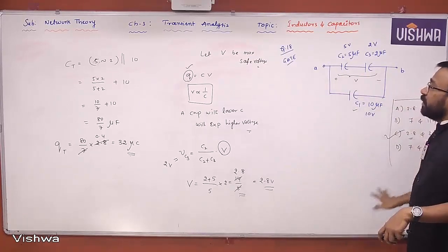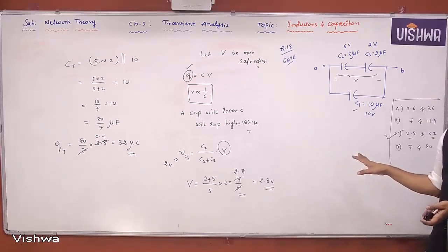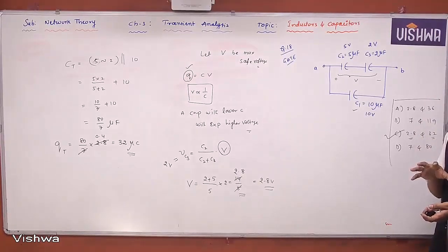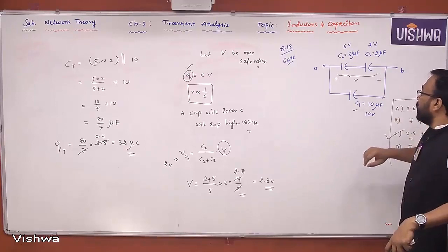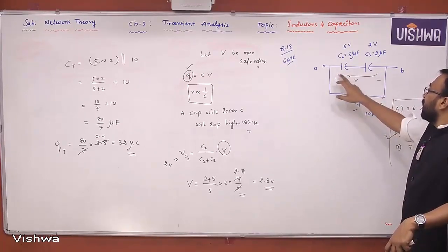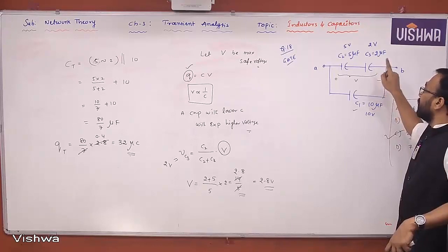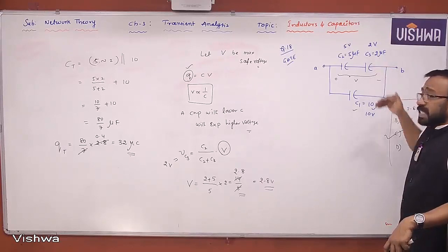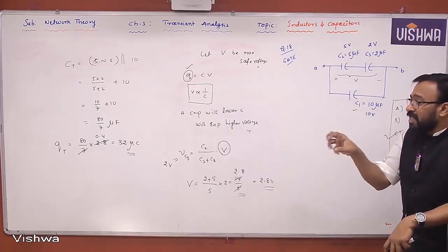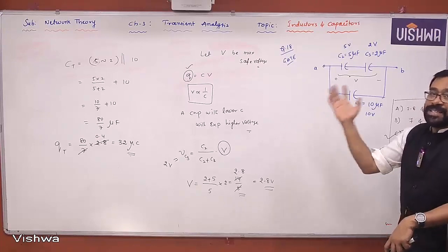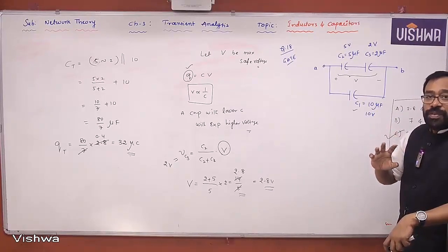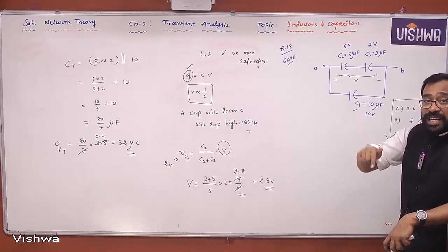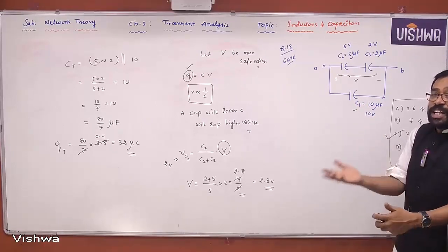So therefore, my dear students, you must be very careful while answering the questions. If you learn the concept, then you can answer the question in any form in which it is asked. What is the concept that we are following here? Maximum safe voltage means, especially when the elements are connected in series, you have to take the capacitor which is offering the lower capacitance into consideration. If you take that capacitor into consideration, you are considering all capacitors. Yes or no, all of you? If the capacitor in danger is considered, then the others are obviously covered too.